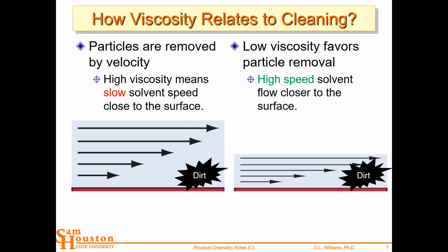And you don't have a high viscosity for the same reason. The fluorine atoms don't really interact with the fluorine atoms on other molecules. And so you don't have a high viscosity, but you do have a high density. In terms of the size of the molecule, you're putting a fair amount of mass in that molecule. And so these fluorinated solvents are great for dislodging particles. That's why the freons were good, the chlorofluorocarbons, and now the fluorinated ethers and fluorinated esters and so on are some pretty good solvents for cleaning.